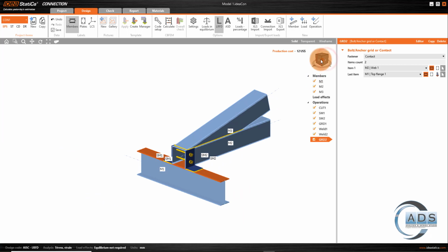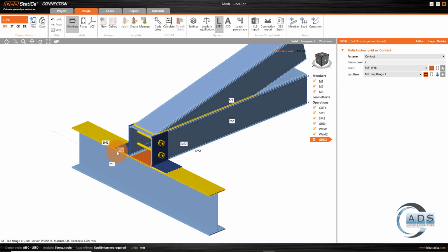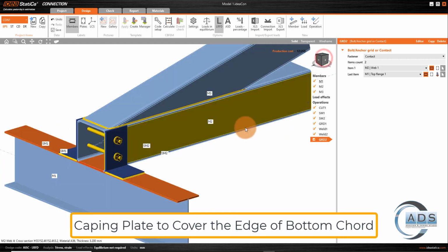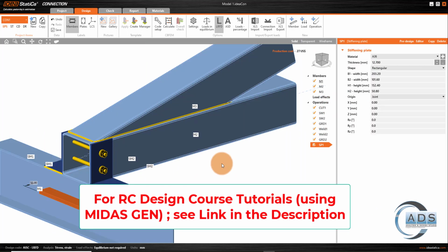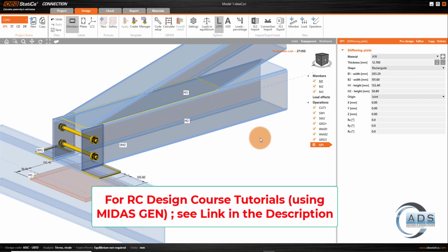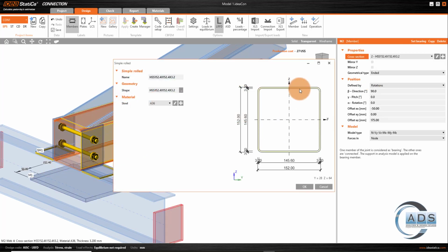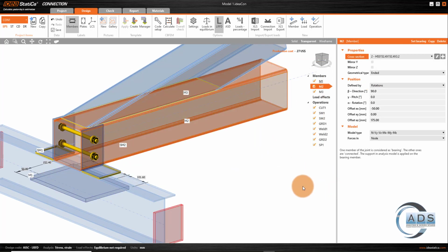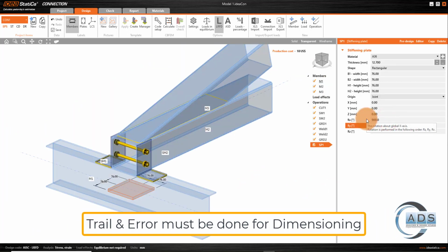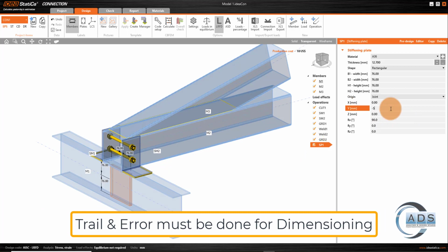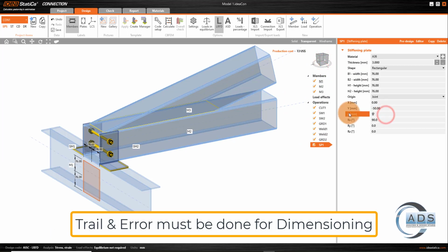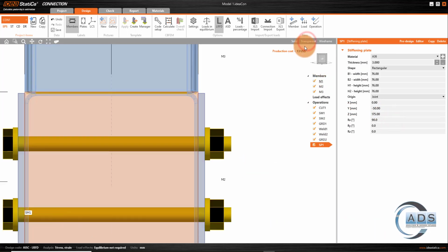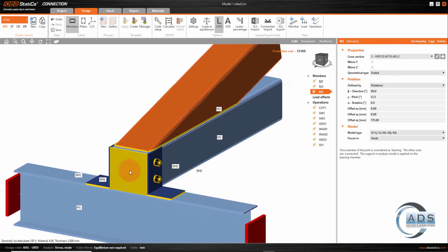Alright, now since on site it is not a good practice to leave this opening as it is, we'll use a capping plate to close this opening. So right click, operations, and go to stiffening plate, transparent, and this plate must be of the same size as that of the tube size, 152 by 152. So half of 152 is 76. It should be on 90 degrees, minus 75, minus 50. It is okay. Thickness, let's just use the thickness of 3 mm because it's only used as capping, and let's set Z offset as 175. It's okay.